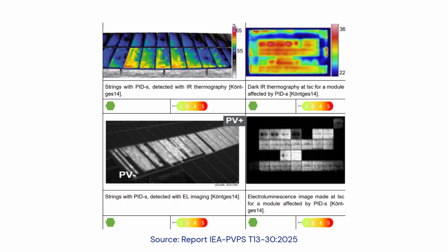Yield losses of 20% and more within 1 year were observed in the past. Due to its catastrophic performance loss, degradation bears a high economic risk. Shunting degradation is to some extent a reversible type and can therefore be partially reversed or stopped when detected in time. However, if detected too late, it can lead to irreversible power loss.